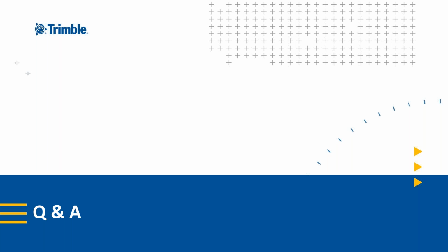Yeah. Okay. And then Matthew asked, when creating the project overview ortho, what GSD do you recommend for a quick overview? I would just use 0.3 or whatever the standard that's already there. As this isn't a product you're going to create, you just want to make sure that you're importing the data correctly. I would not even use a high GSD. I would use 10 or 0.3, I think is what it's set as default, because you just want to process it quickly to make sure your images are oriented correctly. If it's taking too long, cancel it and then select something higher.